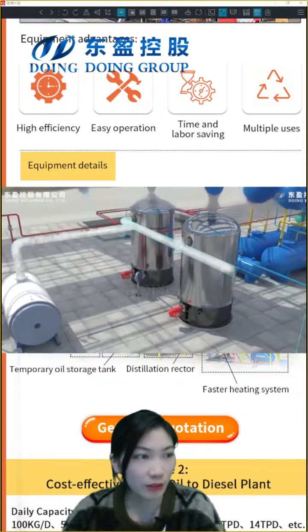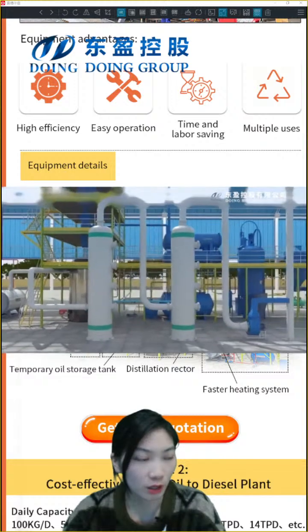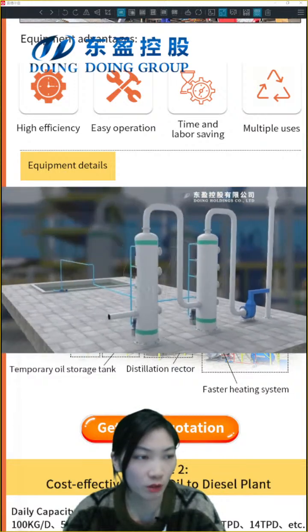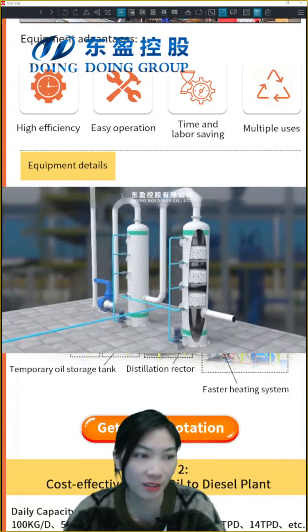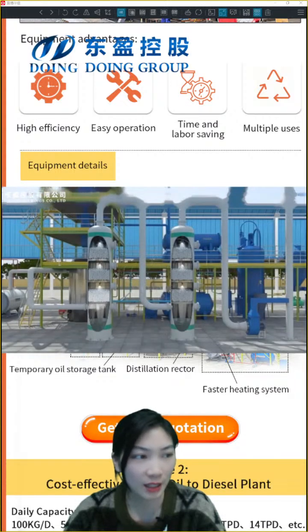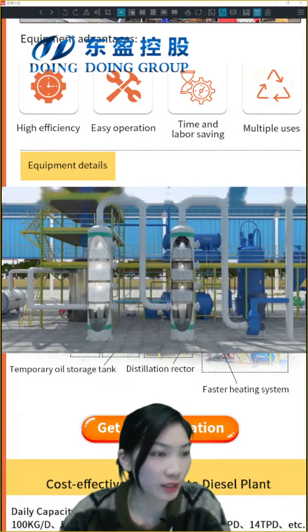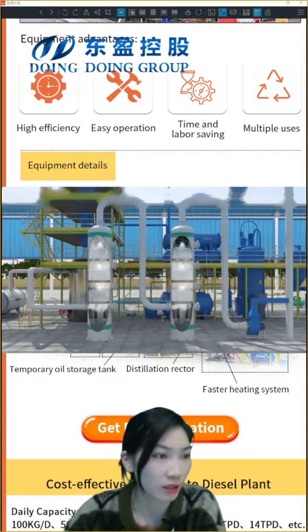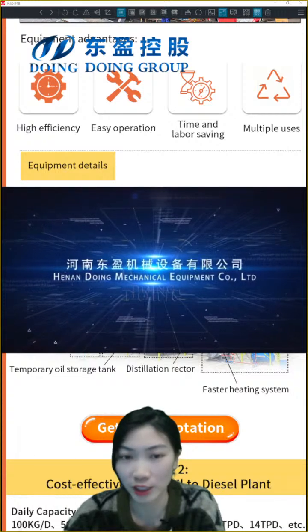Okay, then during this time we also have the flue gas. The flue gas we also call the smoke gas. This smoke gas would flow into the air, but before the desulfurization tower, it is pollution. So now we use a desulfurization tower to clean the flue gas. The flue gas passes through 3 levels of spray tower, then flows into the air.